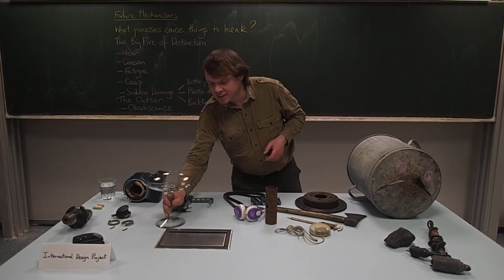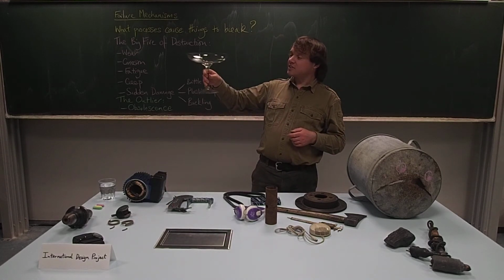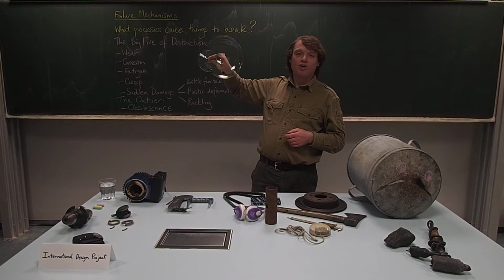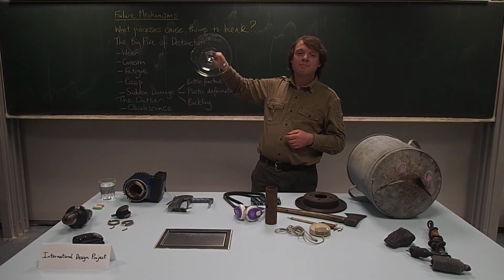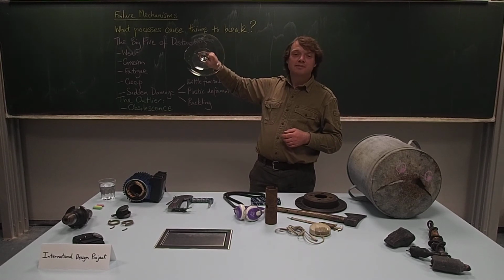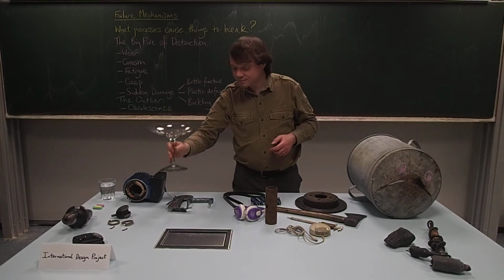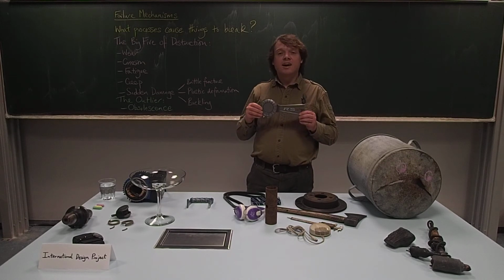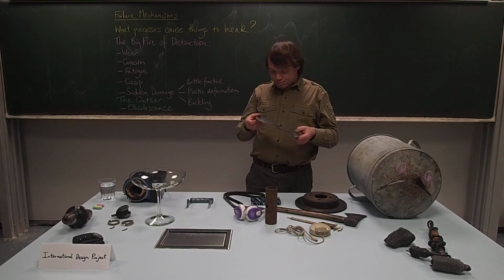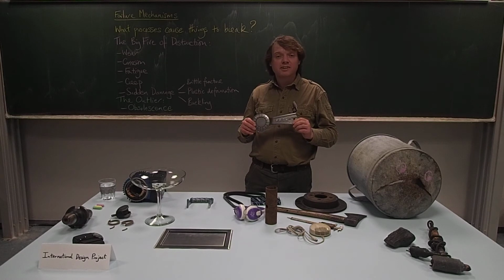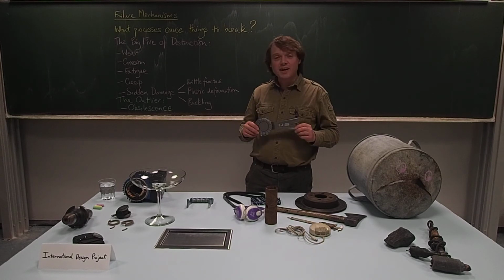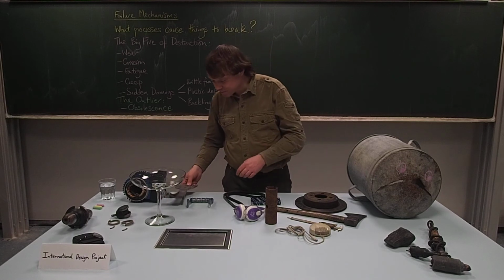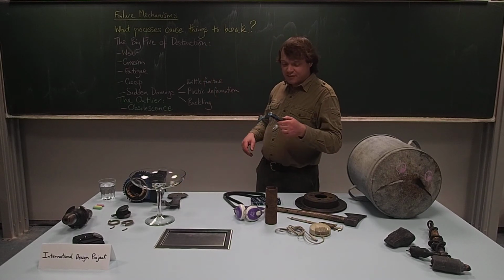And it can happen in three ways. You can get a brittle fracture. Like here you can see this pretty glass dish. It's been dropped and a piece is just broken out of the rim. You can see there's been no deformation of the material, it's just broken off. You can see a similar thing here with this part of a car wheel disc. Again, a brittle fracture. And this is probably something like ABS or some polymer blend. I don't know which one, but something which is quite brittle, and when it's hit a curb, it's shattered into pieces.